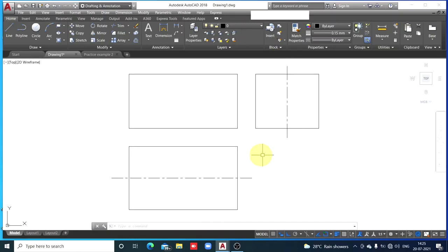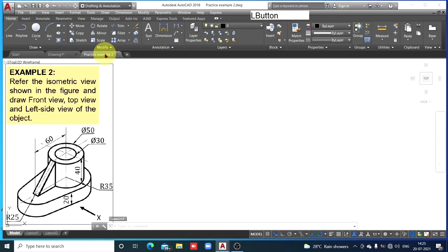Okay, now we are ready to draw front view, top view, side view. Check the drawing. Clearly there are three parts we can see here. Base plate. In top view it shows its shape, and in other two views this plate will appear as thin rectangular strips because it is a plate. So in top view its shape will appear, and in other two views this base plate will appear as rectangles.